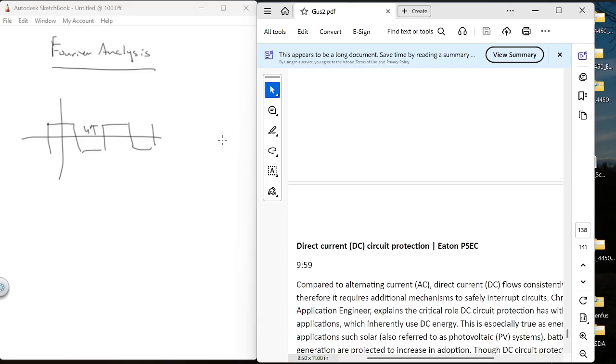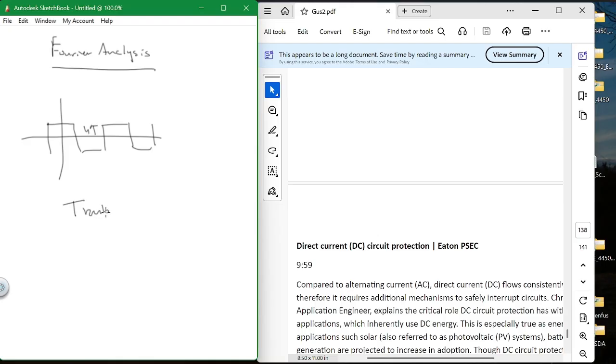Harmonics also play a part in a number of areas in troubleshooting. They call it fast Fourier transforms, FFTs. You can put an accelerometer on a motor and it will tell you when the motor is going to fail. You can also do a fast Fourier transform of the AC waveform of a generator, and it can tell you when it's going to fail.